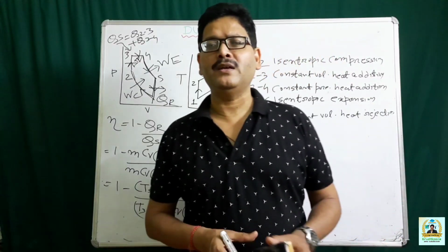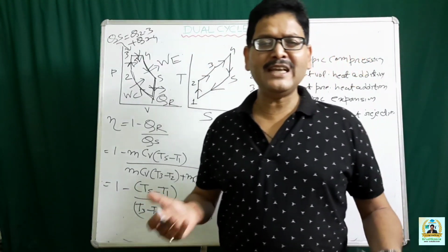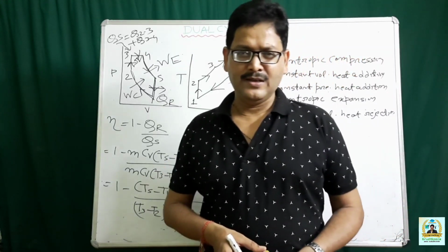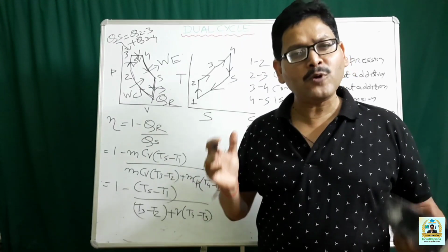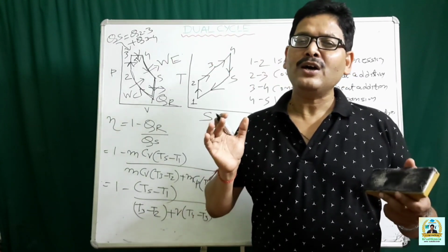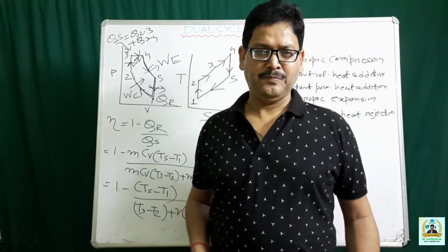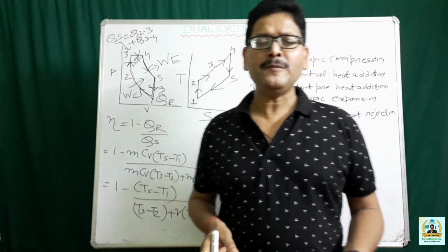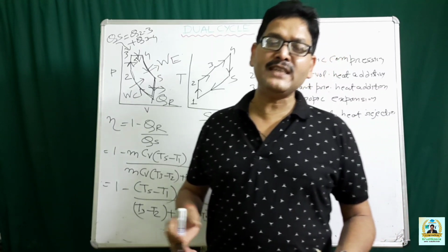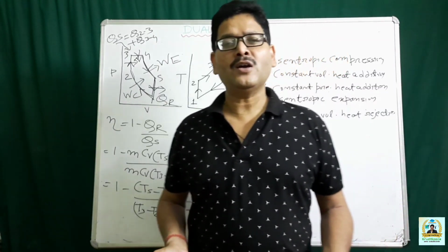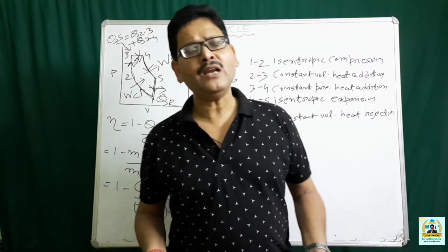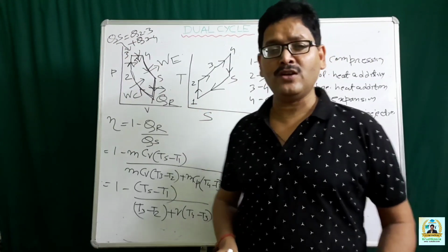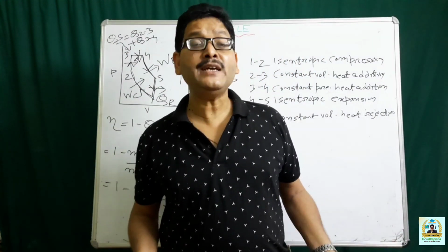One thing that you should remember, contrary to the general perception that the dual cycle has limited application, is that the dual cycle actually approximates the compression ignition engine, because the heat addition is due to compression and the fuel is actually injected before the compression process is over. So in an actual compression ignition engine, some portion will be constant volume heat addition followed by constant pressure heat addition.